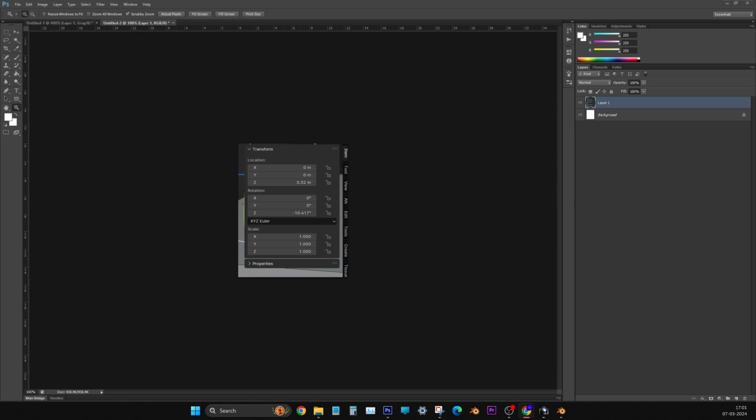So what is happening is you are here trying to move the empty manually. You are selecting the handle, the Z axis handle, and then moving it manually. You are getting the same result. In relative offset, there is no handle, there is no empty or anything. In the viewport, you cannot do that. Only in the relative offset fields, you are typing 1.2 and getting the same result. So there you are typing, now you are moving manually, right?